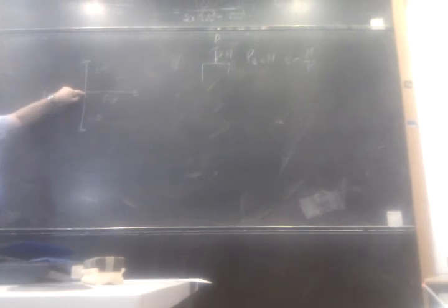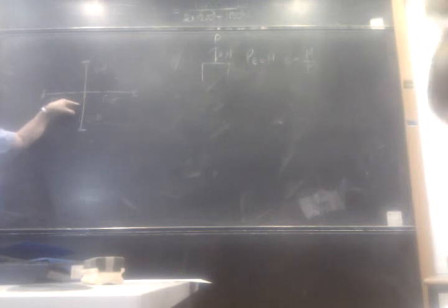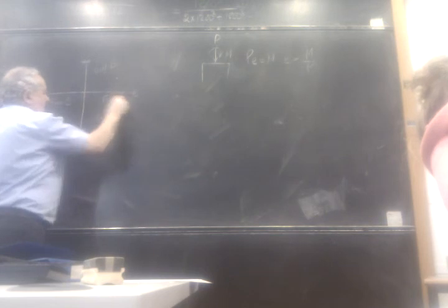Okay, so what we need to do is calculate the out of balance moment here and share it into those four walls. We do that just using the distribution factor we've used in moment distribution. Now it's a long-looking formula if you look at it in the notes, but in fact all it is is a distribution factor. So let's call that B, shall we? A, just to differentiate them. C and D.